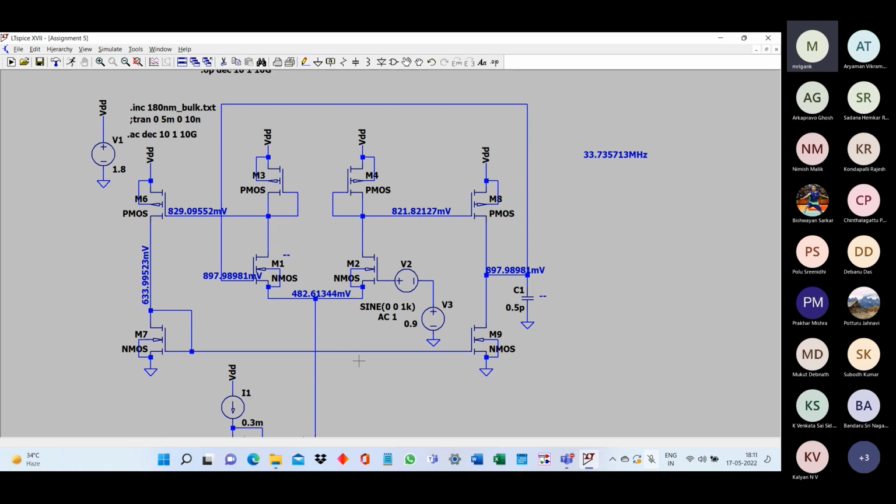We have already gone through most of it. The R value, as I said, does create a high pass response towards the lower frequency, and it does interfere with your closed loop response to some extent. But again, that is just for the sake of DC biasing the open loop artificially. So we have removed it and done it without that. That is also okay. This strategy is also okay.